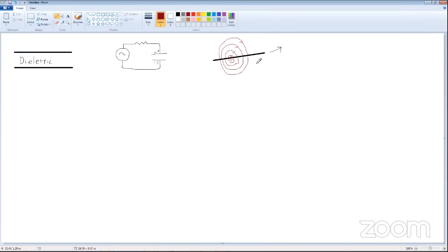So now basically inductance is the number of field lines that get generated per amp of current. That's all inductance is: for however many amps I put here, how many field lines do I get? Depending on the conductor, you'll get more or less. Some conductors are very efficient or have a high inductance as an intrinsic property. Others have a lower inductance as an intrinsic property. But inductance is just that ratio, the number of field lines to the amps running through the conductor.